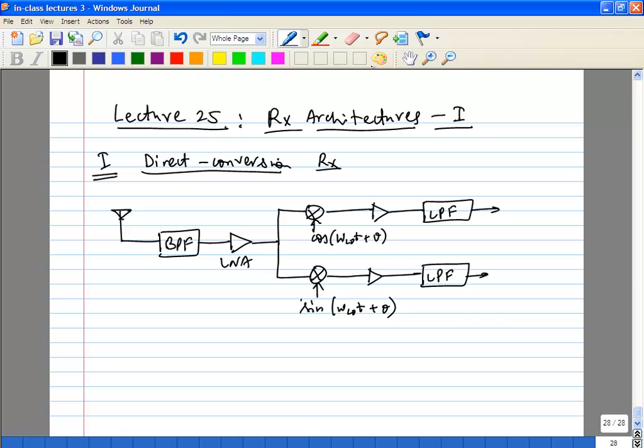Well, it depends on the level of out of band interferers you can actually handle at the input. Remember the LNA has a somewhat narrow band match at the input, but it will be limited. You'll typically need to knock down signals by 40-50 dB, maybe higher. The LNA will not give you that much. It will just help things along. It's meant to amplify, it's not meant to be a filter.